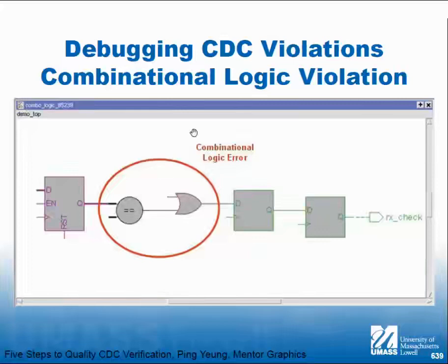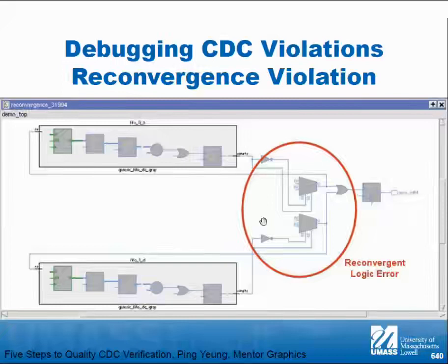This is a pretty good paper. Reconvergent, right? So you have two separate paths. This is a bad idea. The last thing that comes out of a given clock domain should be a flip-flop, right? You shouldn't have logic after the flip-flop that's going into the flip-flop of a different clock domain, right?